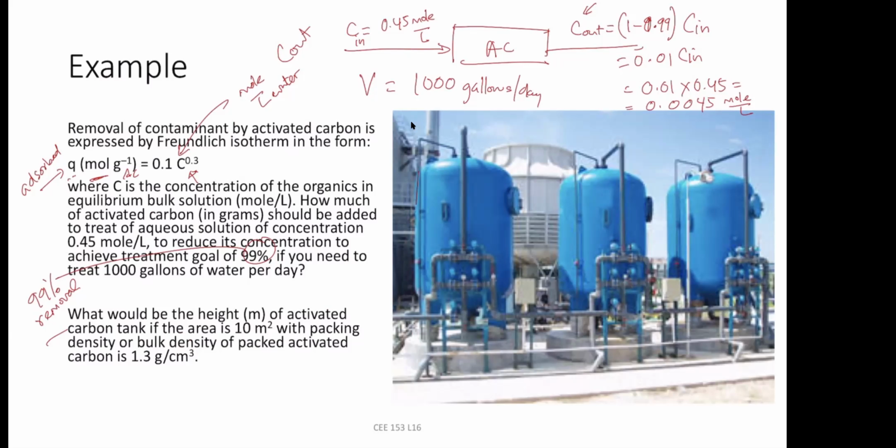Another advantage is that once one activated carbon tank is exhausted, you don't have to wait and stop the entire treatment. All you have to do is bypass it and remove that and put in another one. That's how they are designed in a series.